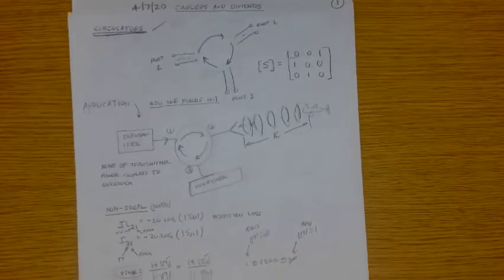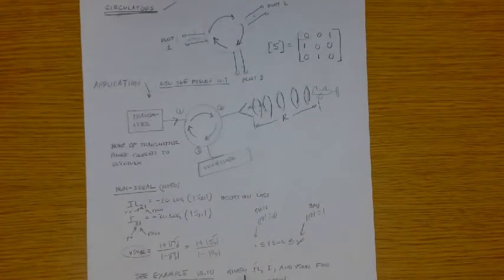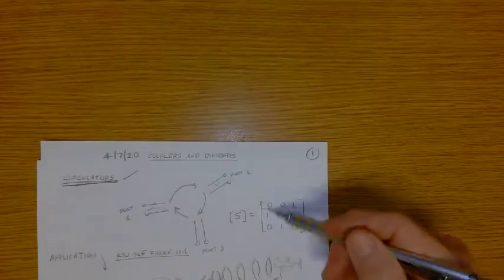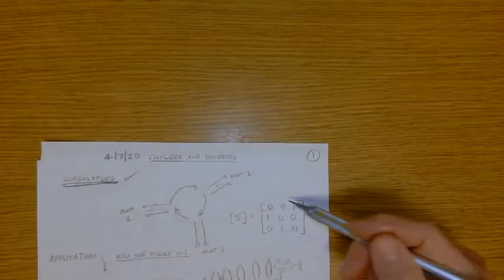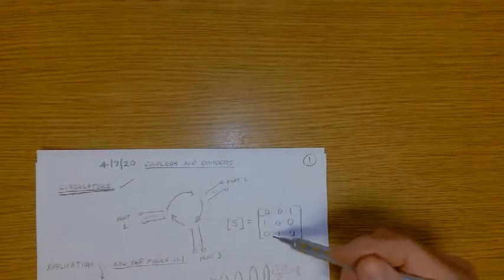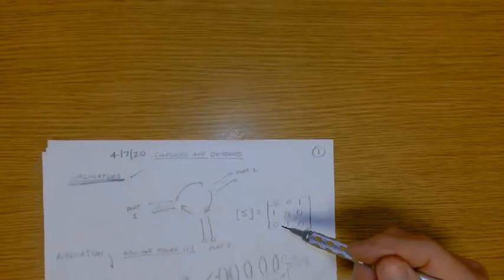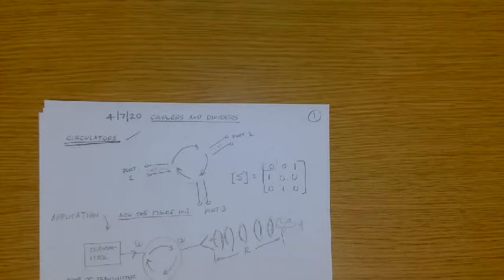So Stu's got a little example in 1010. Look at that. Given the insertion loss, isolation, and the VSWR, find the scattering parameters. Well, if we know these numbers, we can simply back out scattering parameters. Then we can fill this matrix up, and we'll have the actual scattering matrix rather than the ideal scattering matrix.